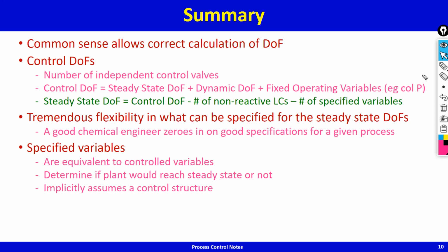If the control valve that is being used to control that particular process variable or specification variable is close by, dynamic response is going to be fast. If dynamic response is going to be fast, control is going to be tight. So the pair close philosophy allows us to synthesize a control structure that holds the set of chosen specification variables corresponding to the degrees of freedom constant.